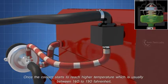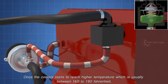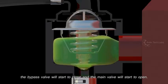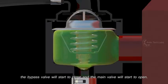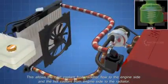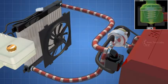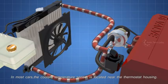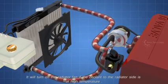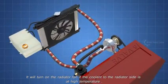Once the coolant starts to reach a higher temperature, which is usually between 160 to 190 Fahrenheit, the bypass valve will start to close, and the main valve will start to open. This allows the cold coolant from the radiator to flow to the engine side, and the hot coolant from the engine side to flow to the radiator. In most cars, the coolant temperature sensor is located near the thermostat housing. It will turn on the radiator fan if the coolant to the radiator side is at high temperature.